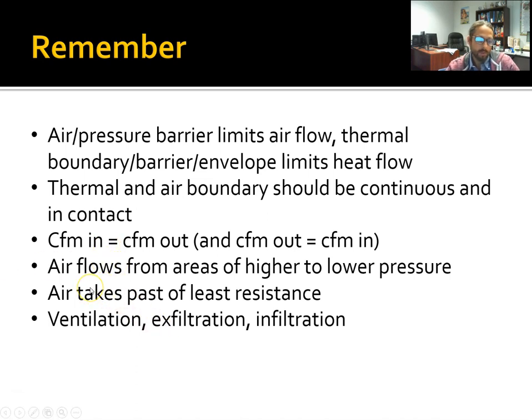Remember that airflow, once you have these pressure differences, is going to find the path of least resistance. If there's a wide open window, it's going to go out the window. If it's a pretty tight building, it's going to find a little crack and find the weak point in the building structure. And remember the difference between ventilation, exfiltration, and infiltration. Infiltration and exfiltration are leaking in and out, and ventilation is mechanical, purposeful, I guess you could say, infiltration.